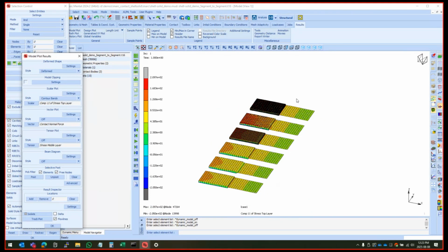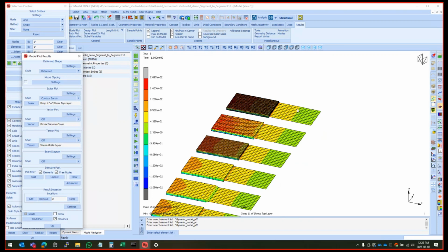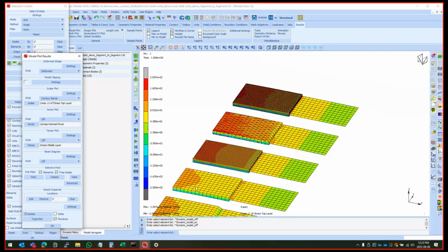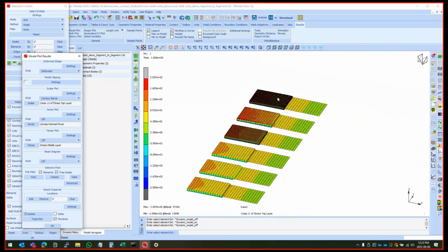Yes. Now I understand. But again, that depends, unfortunately, on the software. Nastran's elements tend to be more accurate. So one through the thickness, I may be able to get away with Nastran. With Marc, as you can see there, we still need a bit more elements through the thickness to get a great answer for first order elements. Yep, like 4 elements in that, I guess, would help.